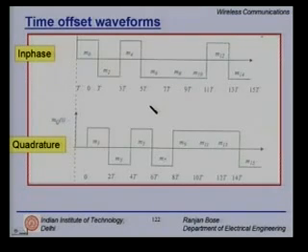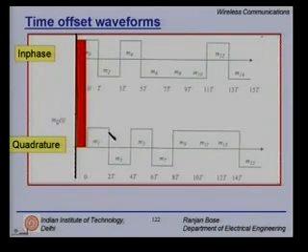I have taken two arbitrary things. But what is important is in QPSK I would have sent this one to in phase arm and this one to quadrature. I do the same thing, except this time for offset QPSK I shift my quadrature bit stream by a small amount given offset,